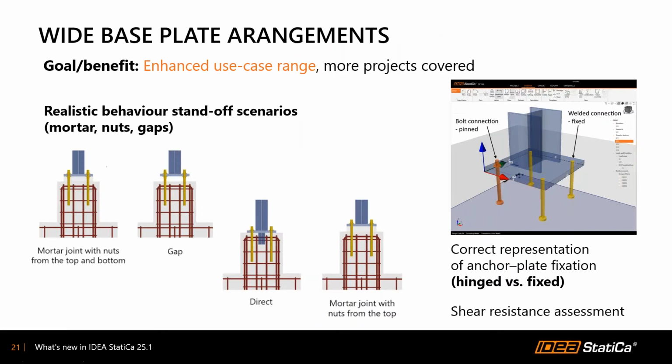Okay, there is more improvement in the 3D detail, because we have enhanced some use cases range based on the base plate export from the connection. What I mean is that Detail 3D now supports realistic standoff modeling for base plates, including mortar layers, nuts top and bottom, and vertical gaps. So engineers can define hinged or fixed anchor plate behavior and accurately simulate the mortar thickness. That's very important. We are enabling you to export the mortar from the connection application, and we are ensuring the correct shear capacity.